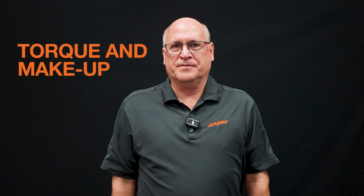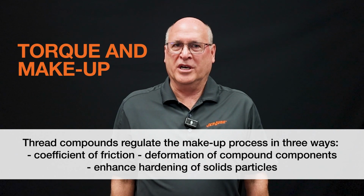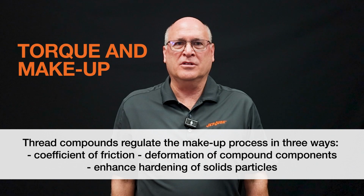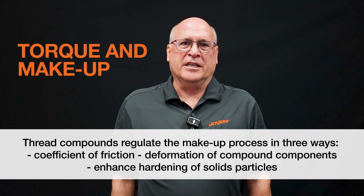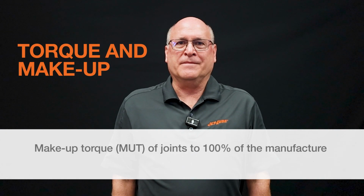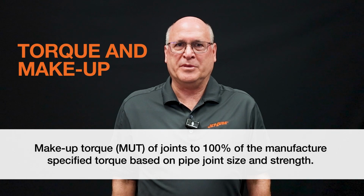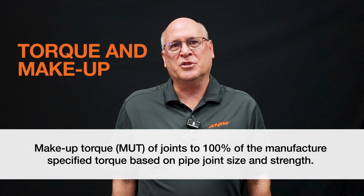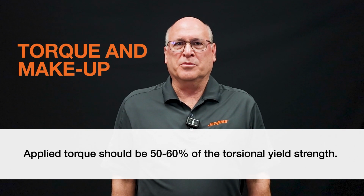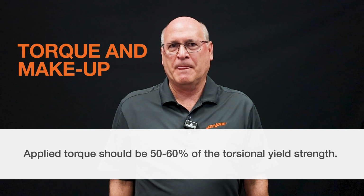Torque and makeup. Thread compounds regulate the makeup process in three ways: coefficient of friction, the formation of compound components, and enhanced hardening of solid particles. Makeup torque, MUT, of joints is 100% of the manufacturer's specified torque based on pipe joint size and strength. Applied torque should be 50 to 60% of the torsional yield strength.